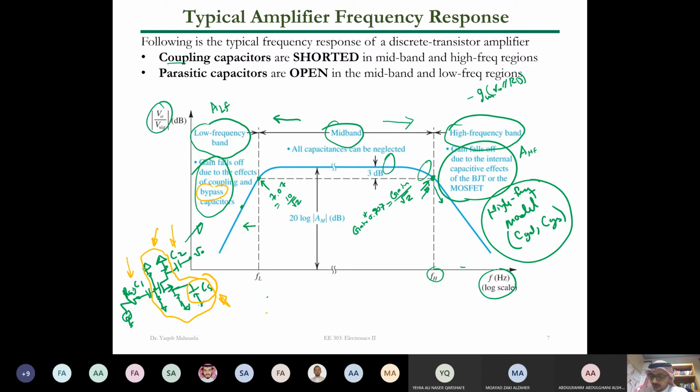Your point is valid. We could agree one day and say, we want to change this to, for example, a 10% reduction in the gain. That would be fine. But what we agree upon is the bandwidth definition. The bandwidth definition is the 3 dB point of the frequency response gain. So we are talking about a definition that exists now as a standard that everyone agrees on.